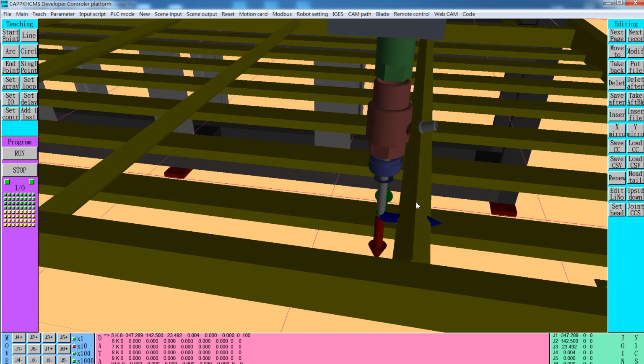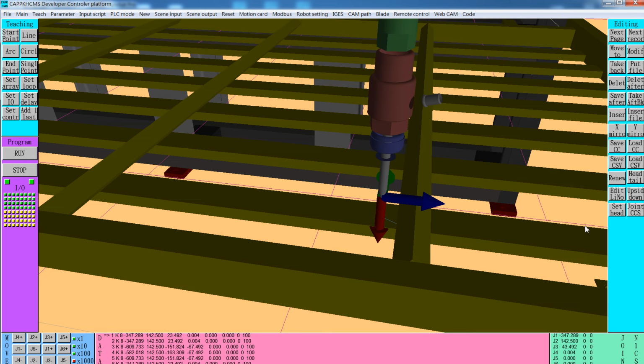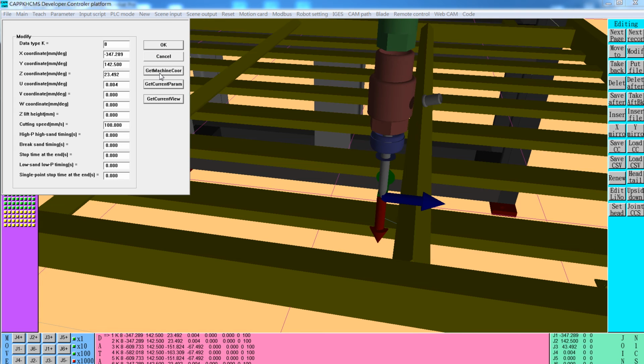These points are higher than 37, so we have to lift in the Y direction twice. So we move to the first line first, and insert 1 extra line in front. The 1 and the 2 are all the same. Change to the fastest speed first. How to retract? In joint mode by pressing J3 plus twice, once, twice, and then modify, replace the first line.